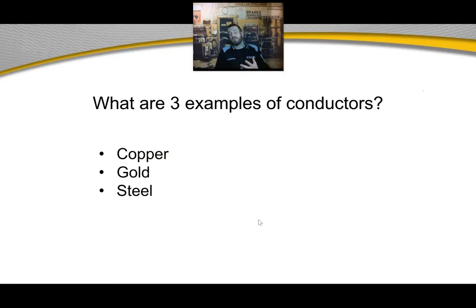It's because gold does not corrode. Copper corrodes, steel obviously corrodes, aluminum corrodes. But gold doesn't corrode, so if you want a good connection that's not going to corrode, gold's your way to go. If you dig up gold in your yard, you say, oh man, look, it's gold, not, oh, here's a piece of rust. It doesn't corrode.